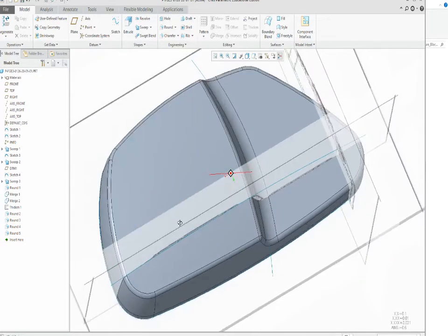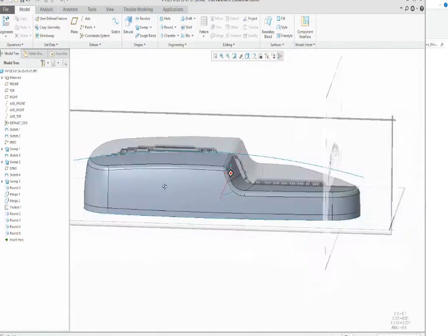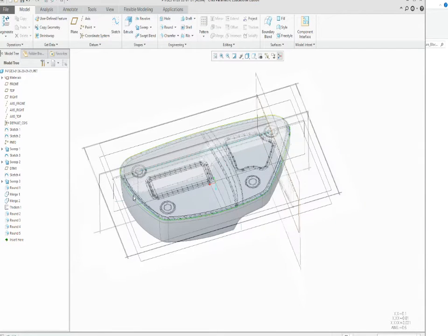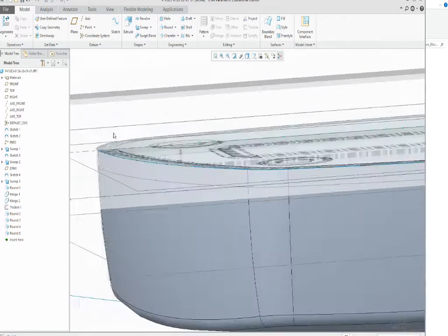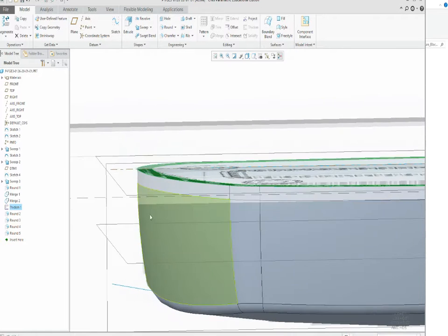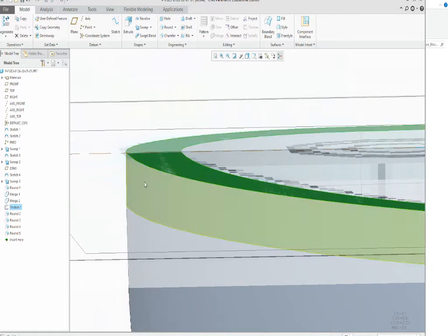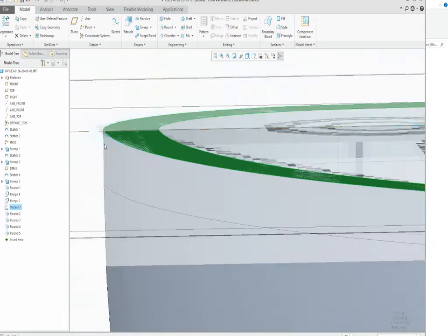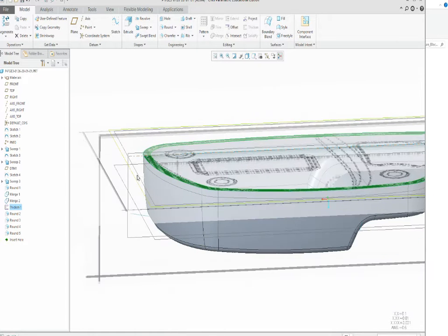It's got a nice look for the design of the profile of the part. Next thing we need to do is fill in the body, but there is a bad thing that happens whenever you thicken something. Sometimes you don't know if this is flat. Sometimes it tapers up. Since we used the line right here that was just off of 90 degrees, more than likely this is not flat. So the best thing that you can do here is chop just a tad off your part.